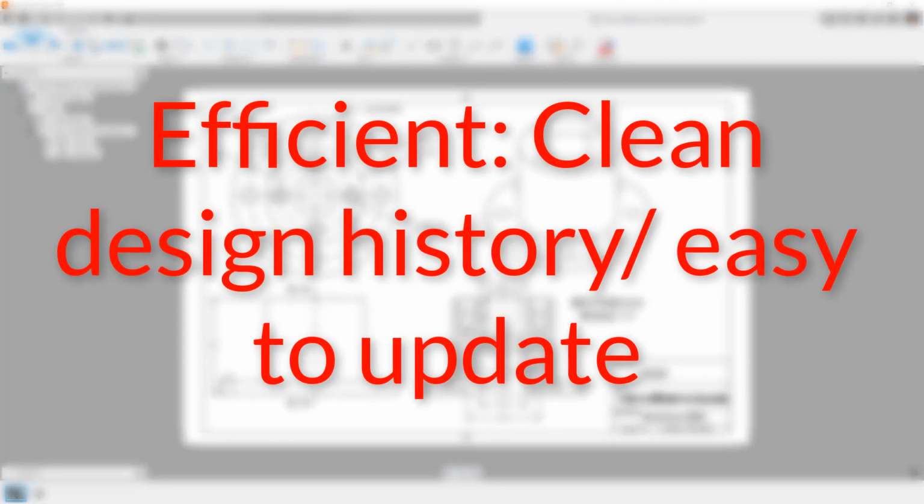The next option is efficient. With efficient, we're talking about a part that maintains a clean design history, something that can be updated easily. If you know that things like draft angle or wall thickness are going to update, this means that you're creating parameters and basing your design on that. You're not exactly looking for speed here. What you're looking for is an efficient model. The speed actually comes from making variations on your design. If you're changing dimensions, take the time to make sure that the design updates parametrically and is efficient, then you can save time downstream by using that approach.